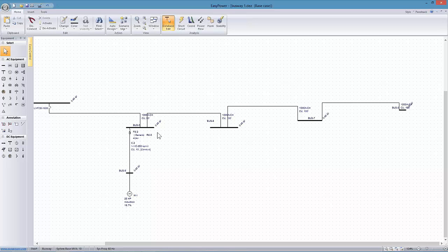All right, then for each of my other loads that are going to be within 50 feet, so anything between the breaker and this first 50 feet of run, and then everything out to the first 100 feet, which would be halfway through this next run, I want to put those pieces of equipment either lumped or individually here.